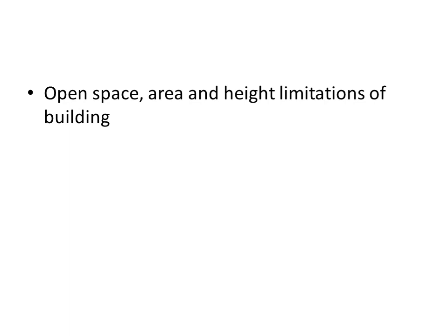Then open spaces for tower-like structures. Notwithstanding the provision of bylaws, tower-like structures may be permitted only with 6 meter open space at the ground level and 1 setback at the upper level, provided that the total height does not exceed 24 meters. If it exceeds 24 meters but does not exceed 37.5 meters, the minimum open space at the ground level shall be 9 meters. Beyond 37.5 meters, the minimum open space at the ground level shall be 12 meters with 2 setbacks at the upper level.